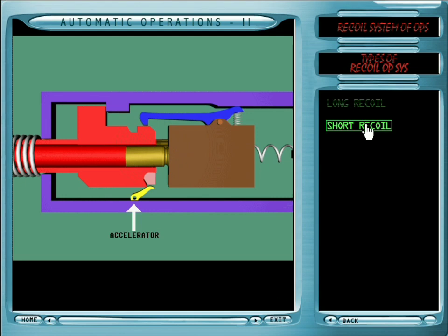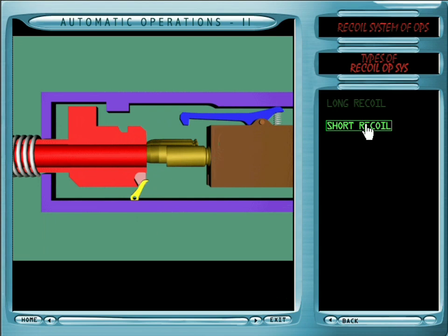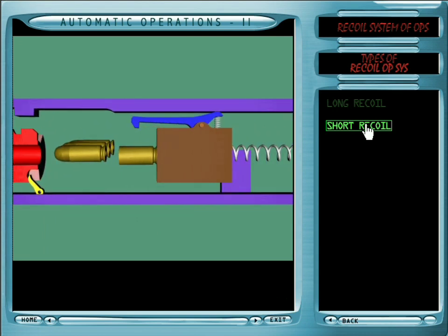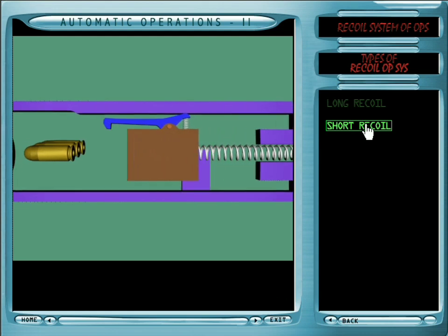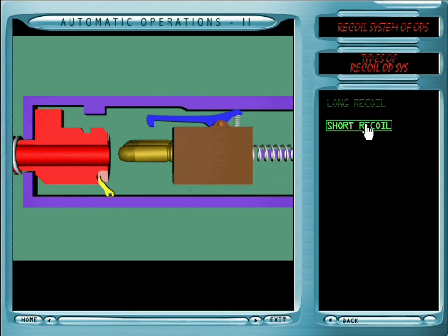When the barrel gets unlocked and moves ahead, it moves in a pivotal motion and provides added acceleration to the breech block in the rearward direction. At the point of the limiter, when the barrel unlocks and moves forward, extraction and ejection take place. The breech block, on reaching the limit of rearward motion, starts moving ahead, wherein it feeds, loads, and locks.